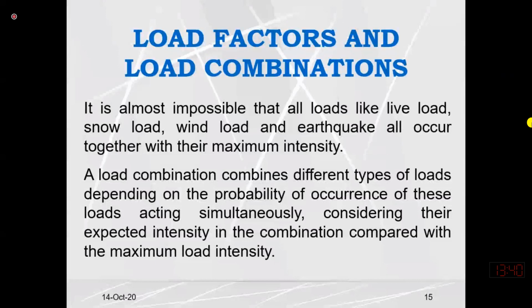If I consider all the loads at the same time, my design will become very heavy, because I am designing for a heavy load. So I have to consider the loads in different realistic combinations. Realistic combination means that when a heavy wind is blowing, there might not be any snowfall. Or when wind is blowing, the effect of the wind may be opposite to the gravity load. It means if the wind load is acting, then a full gravity load may not be acting. There might be some uplifting effect.